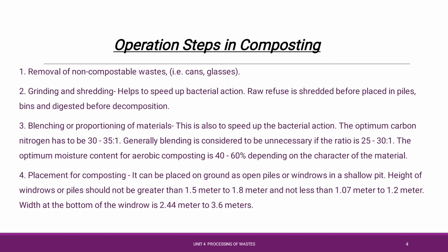process. The optimum moisture content required for aerobic composting must be within 40 to 60 percent. After that, placement for composting.